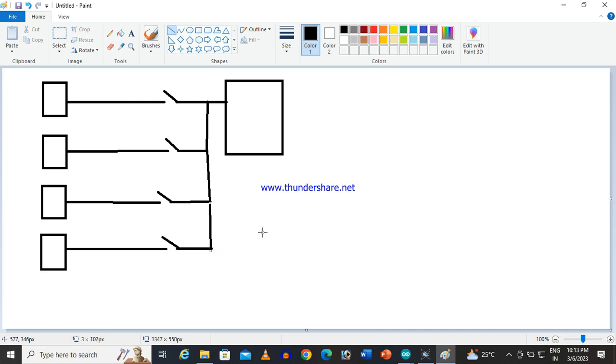So it is like that, and definitely here in between some signal conditioning modules are there, because in case of thermocouple this output will be millivolt, but in the controller ADC, the reference voltage will be either 0 to 5 volt or minus 5 to plus 5 volt or 0 to 10 volt, like that.